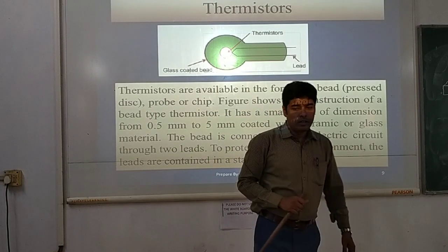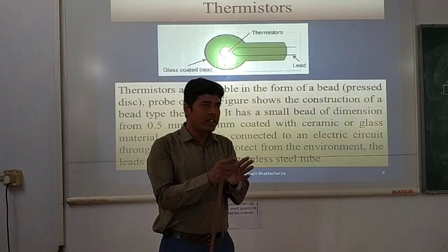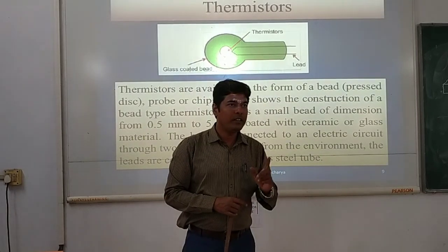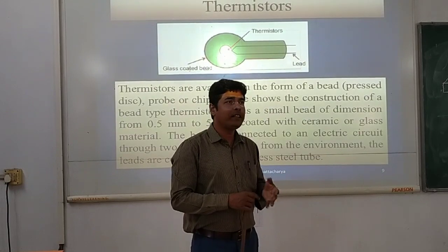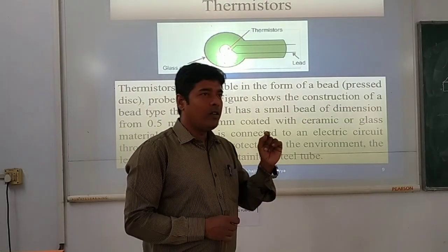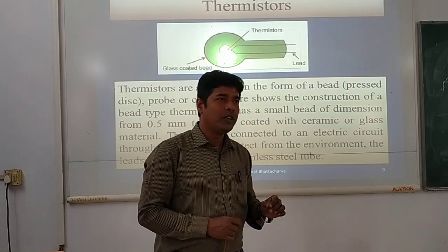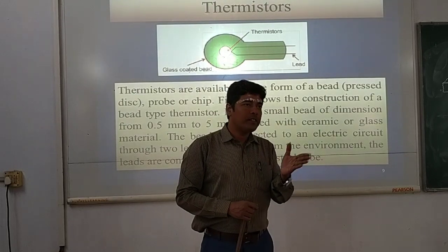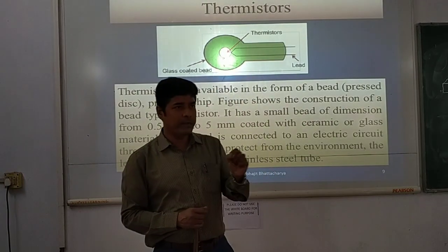Suppose you are doing some experiments to measure the temperature at various points on a cutting tool. You are doing machining operations, and you are performing an experiment on how temperature is generated at different points of the tool. Accordingly, some decision can be taken. So on the rake surface of the tool at different points, or the flank surface, you need to find the temperature. As you want to find the temperature at different points, you can attach these sensors by making some holes.